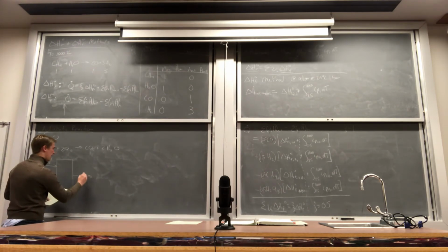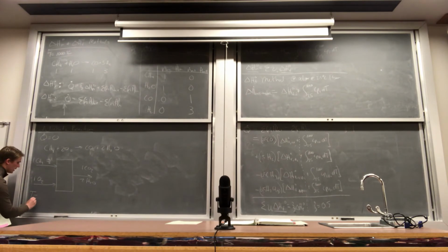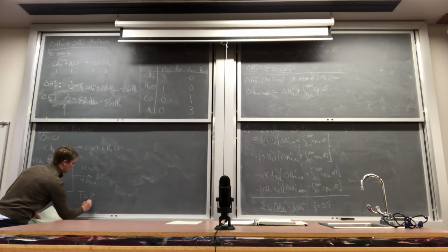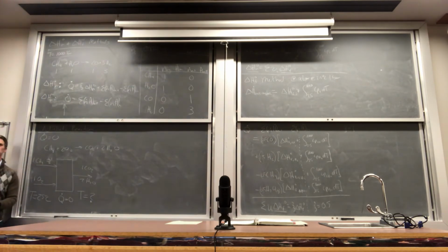And leaving, I have my 1 CO2 and my 2 H2O. I'm going to say this T in is at 25 degrees C. So imagine that I have a burner, like I said, a Bunsen burner just sitting in the lab. You have a natural gas feed line. It's grabbing some oxygen from the atmosphere. And out here, we don't know what the temperature out is, but we're calling this an adiabatic reactor so that Q is equal to 0.